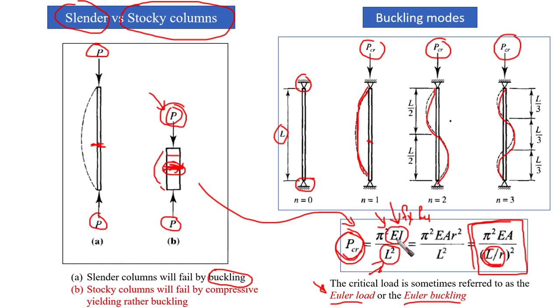Remember that E is Young's modulus, the slope of the stress-strain curve for the steel, which is going to be constant for all types of steel. So all types of steel have this constant E. That's very important, so keep it in your mind. The critical buckling load has to do with EI, the inertia, and the length. Up till now it has nothing to do with F yield or F ultimate of the material itself. Keep it in your mind, and I'm going to recall it later.